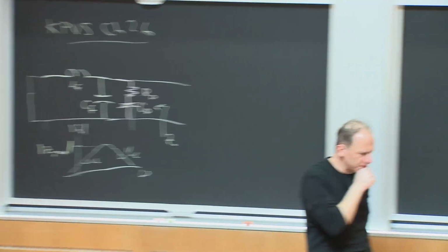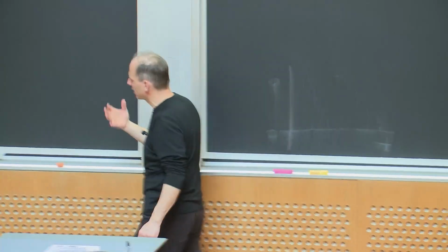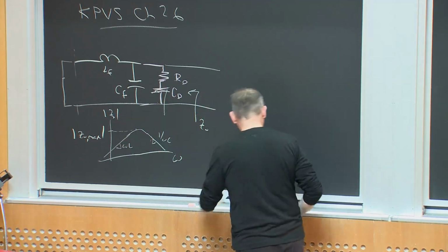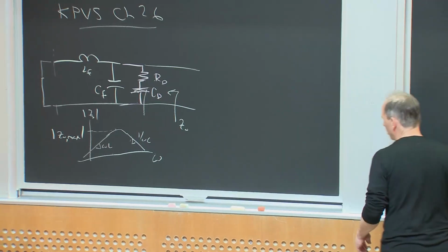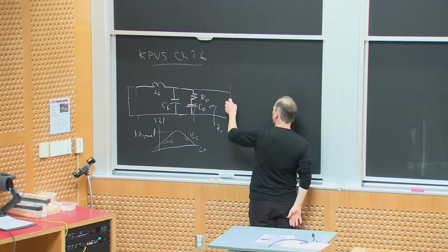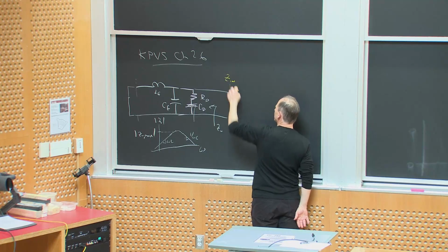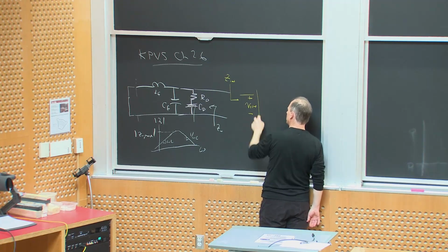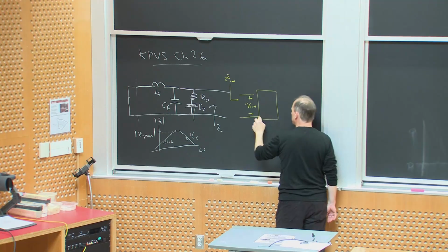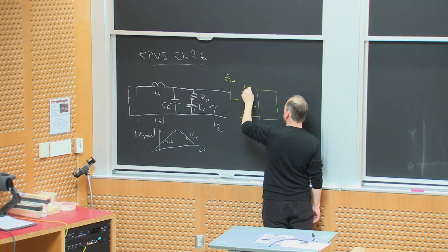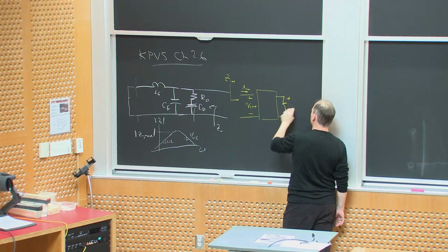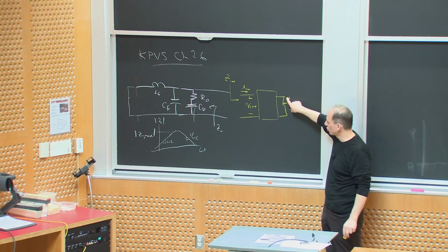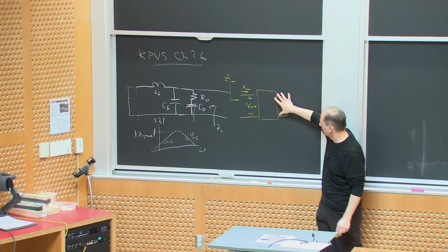Now, the reason we care about that is both because we don't want a lot of peaking and undamped behavior in this filter, but also because if I look in the other direction into the power converter and ask what the input impedance looking into the power converter is incrementally, with some V in and some I in to the converter, and the converter is regulating, it's going to maintain a constant voltage across its load, or equivalently, draw ideally constant power.